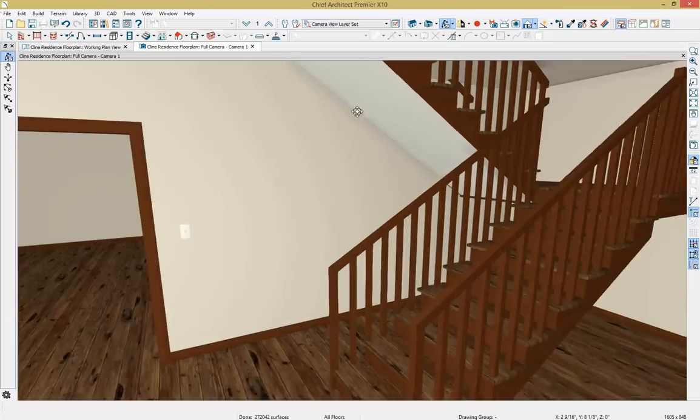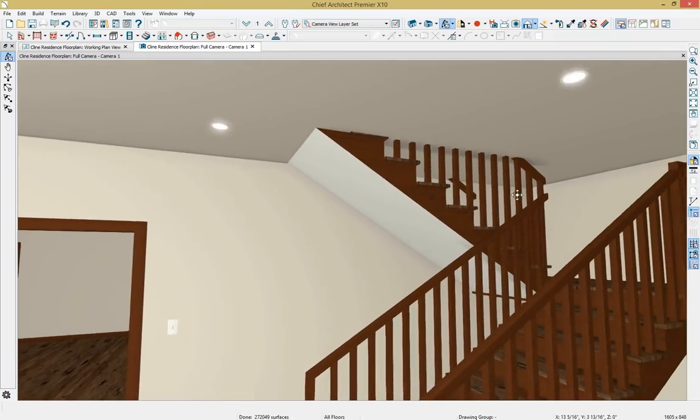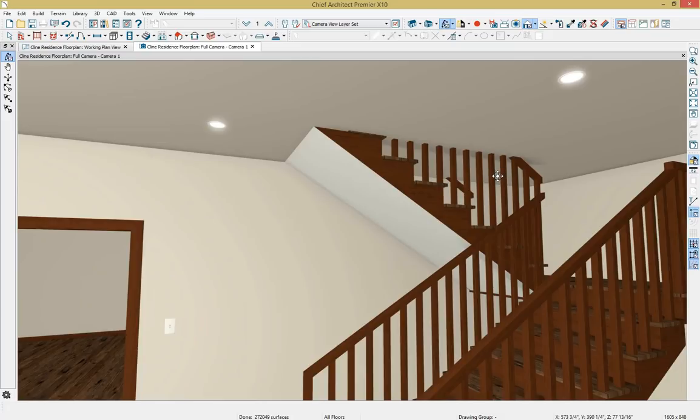and if we look in our 3D view, we can see that the stairs are not yet connected to our second floor and that we need a stairwell here. There's a really convenient feature called Auto Stairwell that cuts a hole in the floor platform above these stairs between the first and second floor, so the software does all the work for us in making sure these stairs connect. So to use this feature, I'm first going to press spacebar, select our stairs, and in the bottom toolbar we have the feature for Auto Stairwell, and I'm just going to click on it once.